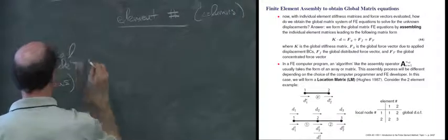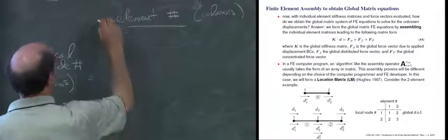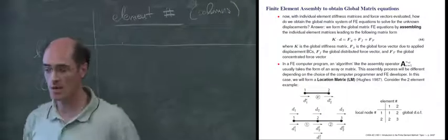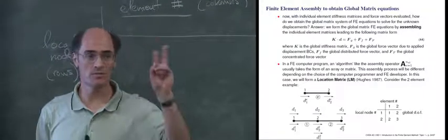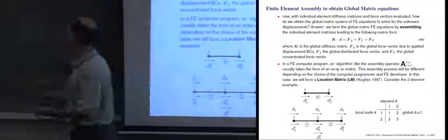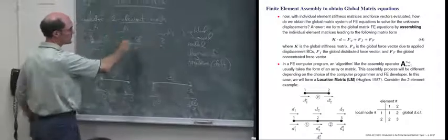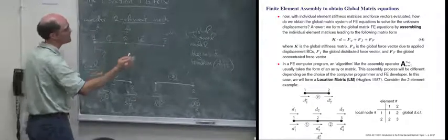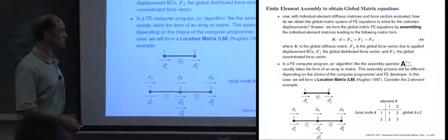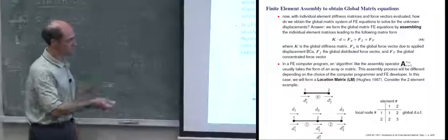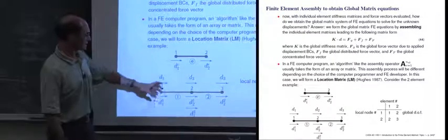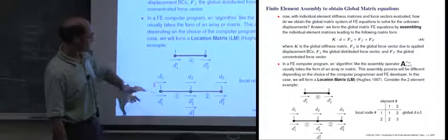So for the local node number, we always have 1 and 2. For the element numbers, it depends how many elements we have in our mesh. So in this case, we just have 2 elements. So you'll see for the examples we'll soon consider, it depends how many elements we chose to divide this length of this bar. So we chose 2, but we could choose 3, 5, 10, 20, 1,000, however you want to do it. And when we get to the Abaqus tutorials, it'll be easy to make that change. But for specific code that you might write, it becomes a little more complicated.